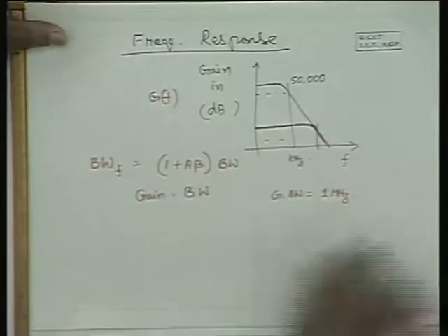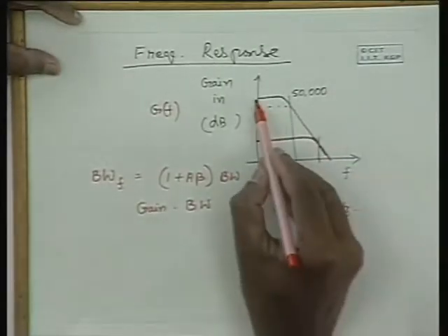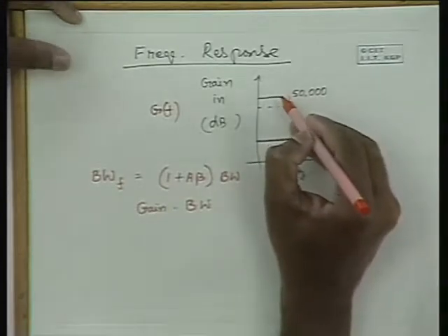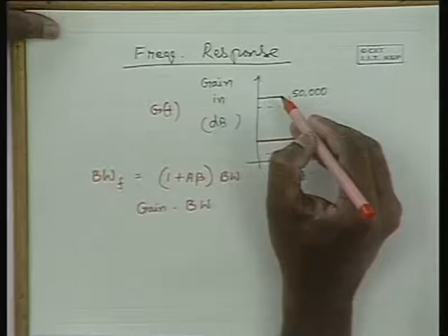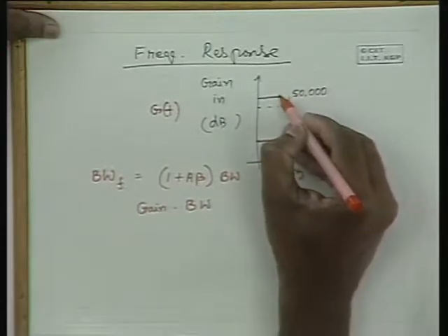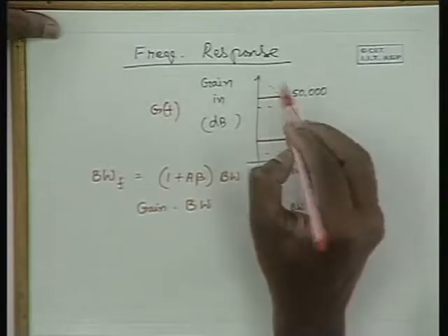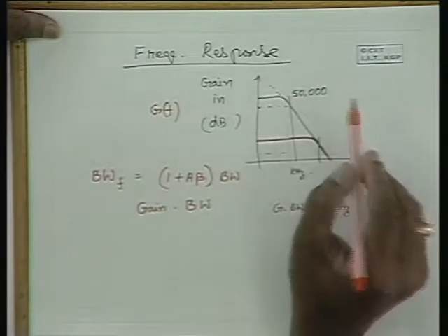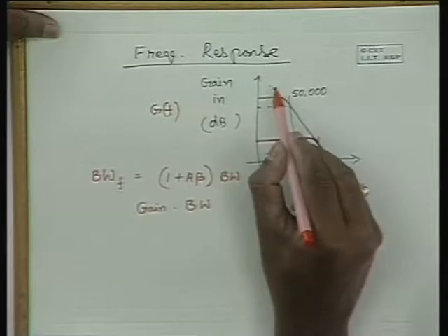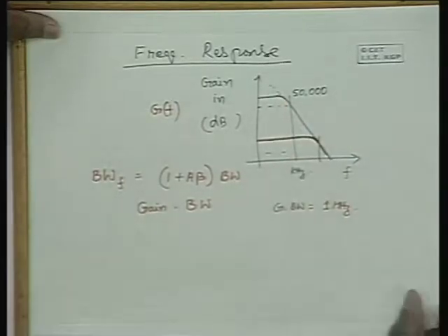region. It is valid only for the slant region, but please note that this is negligibly small, and that does not mean that for 0 voltage you get infinite gain. So if it were so, this curve would go up like this. So the gain bandwidth product being constant is applicable only beyond certain frequencies. It's not applicable for low frequencies.